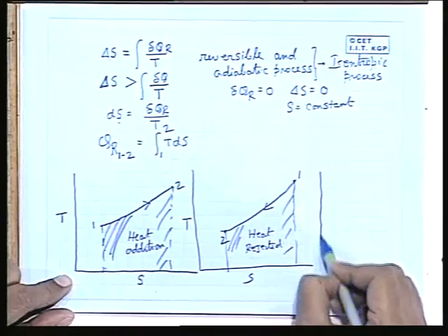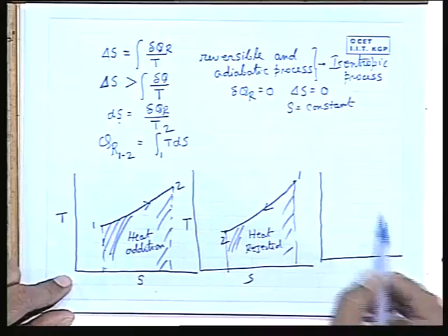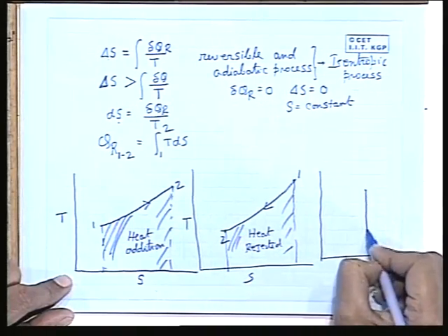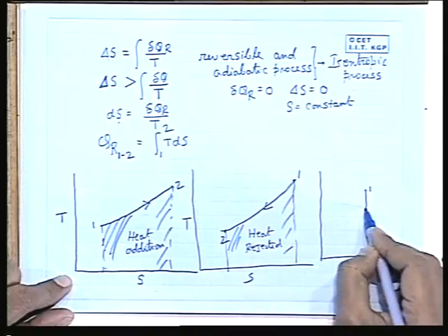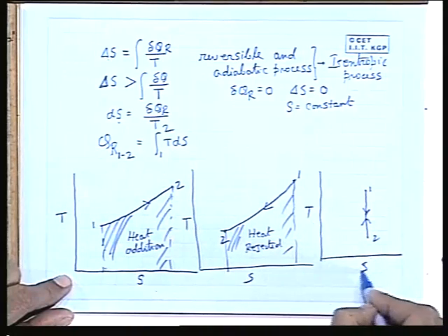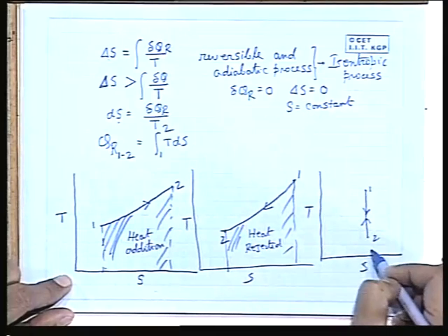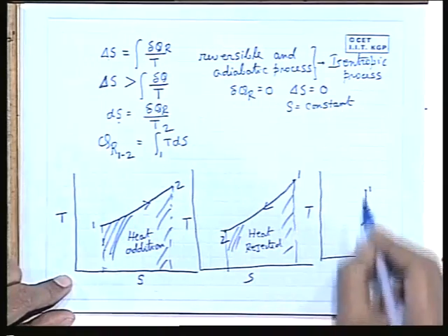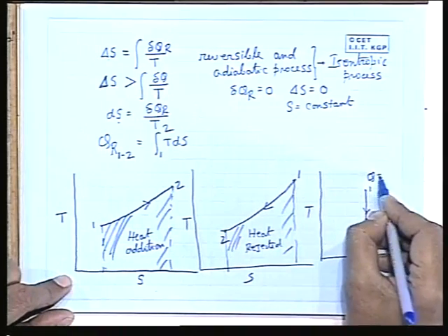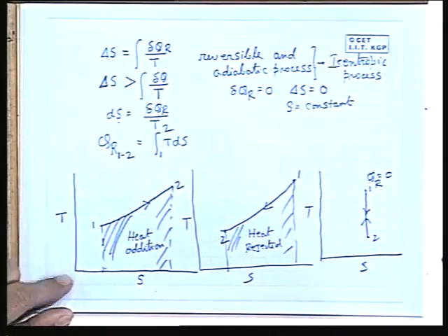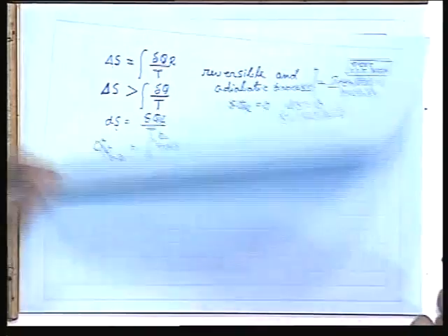And if a reversible process does not interact heat, that means a reversible adiabatic process, we know entropy remains the same. That process will be either an expansion or a compression, where temperature will increase or decrease. It does not have any heat transfer, so Q R is equal to 0. This is a line; there is no intercepted area on the TS axis. So, these are very simple.